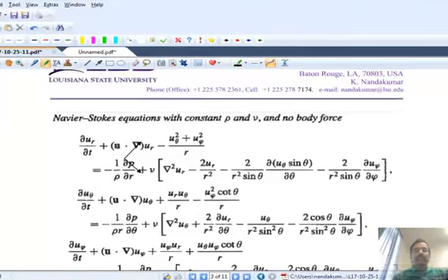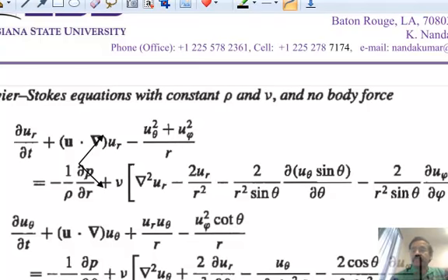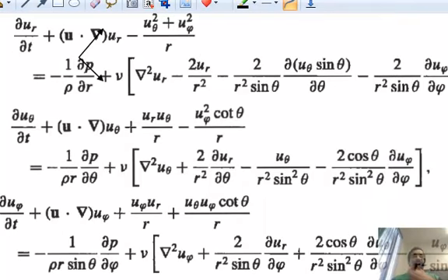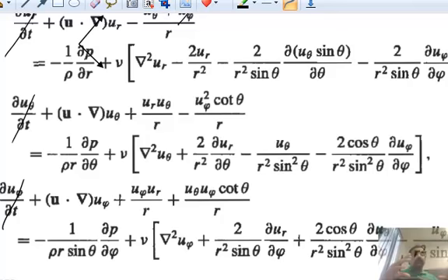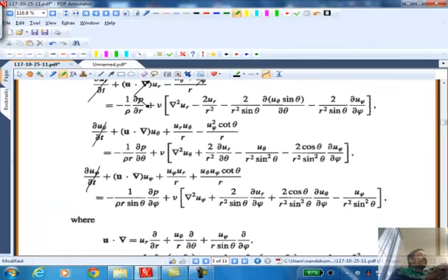Okay. So, once again, taking the Navier-Stokes equation, we start simplifying it subject to those conditions that the flow is steady and there is no phi component. So, wherever you have phi component, you drop that out and simplify the Navier-Stokes equation. Now, in going through the solution, I'm actually giving you a little bit more information than is found in Bird-Stewart-Lightfoot. But still, I expect you to fill in a lot of intermediate steps, because if I'm doing every step of the algebra, we'll be spending 4 lectures on this because it's a fairly long problem to solve.